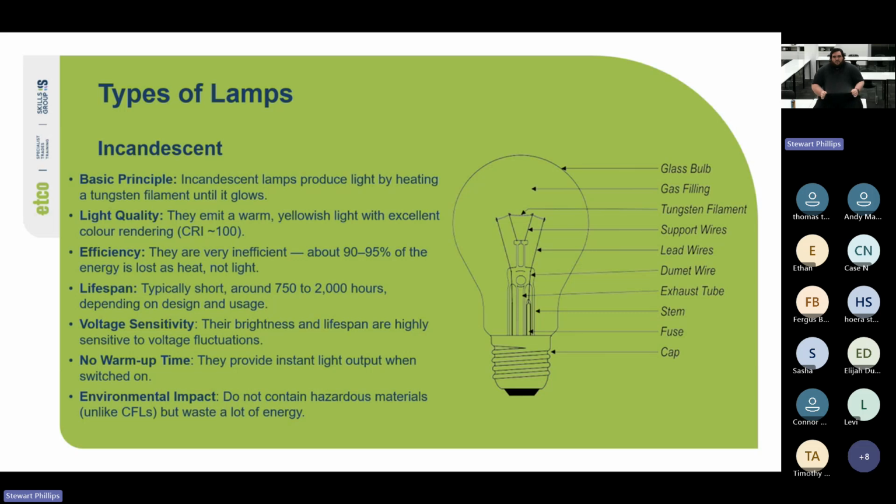There's one important rule when we wire up Edison screw light fittings that has to do with the way the pins are wired up. Polarity, yeah. L to the center pin, yeah. The reason for this is as we screw it in, the threads on the outside could become live if we have the phase and neutral swapped. This means that someone could accidentally touch.